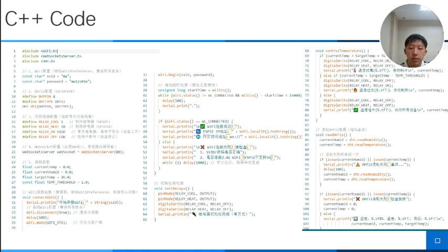After receiving the command, in the loop function, the loop operation of NetPie is maintained, and serial port data is monitored at the same time. When temperature and humidity data uploaded by the sensor is received, it is published to the status topic through NetPie.